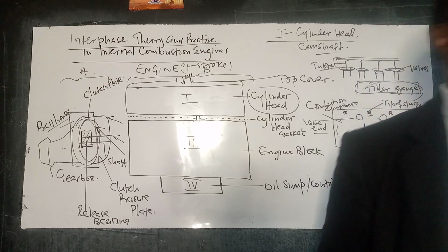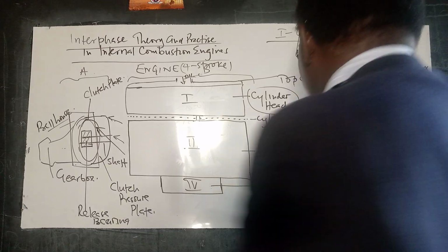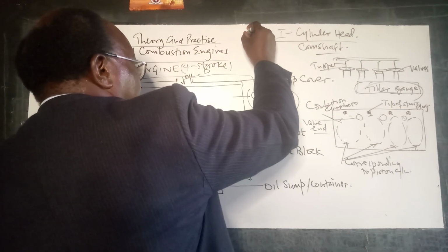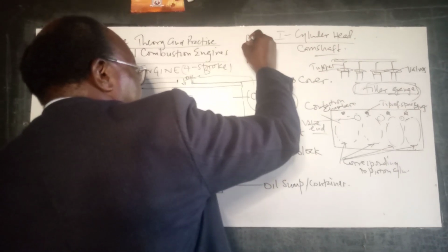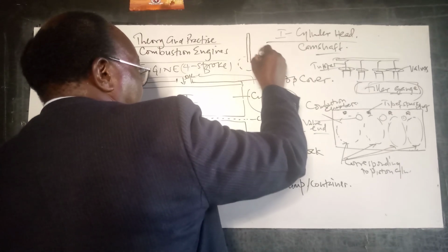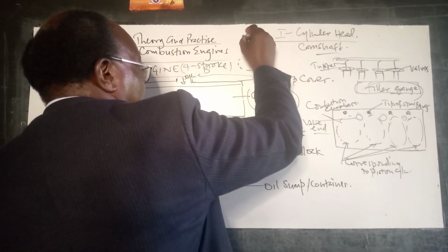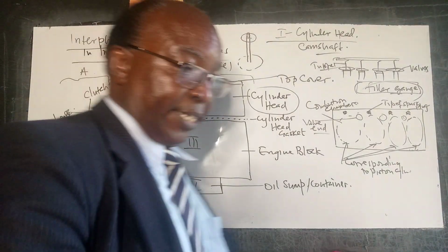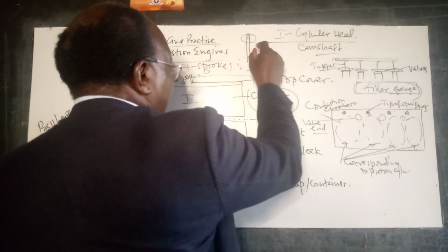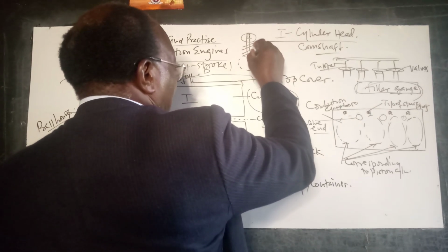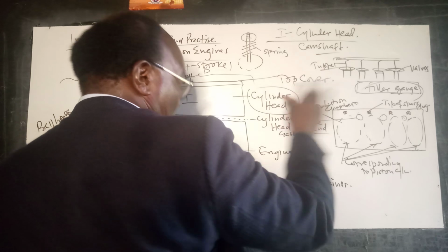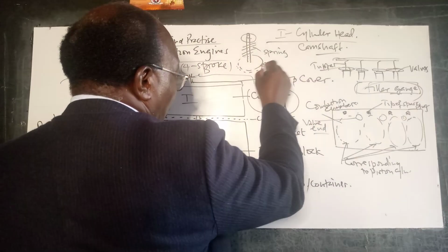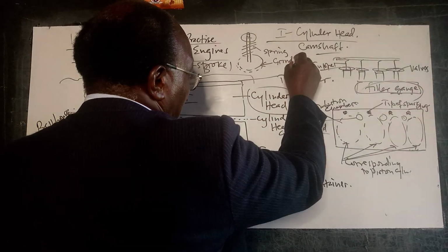And to grind them, there is a paste which you smear on your valve. Remember, your valve. Let me try to do it as best as I can. And these are grooves where you put the valve lock to lock it. And then, of course, there's the spring. When it's mounted on the cylinder head, the bottom here is normally sooty, so we do the grinding using a paste.